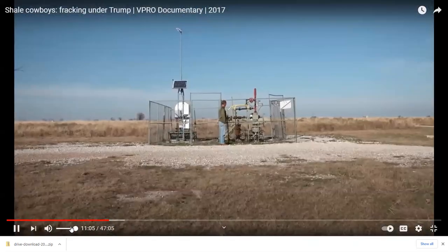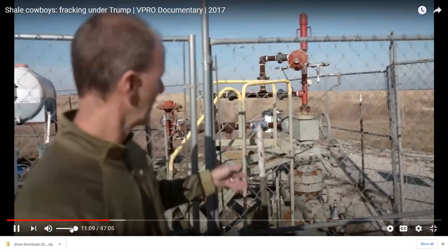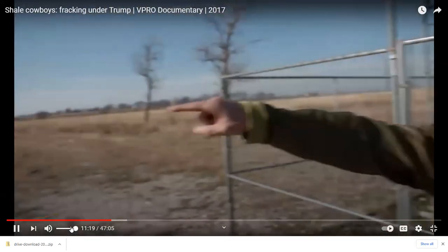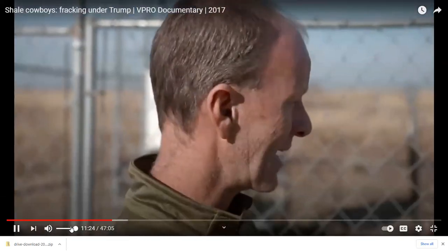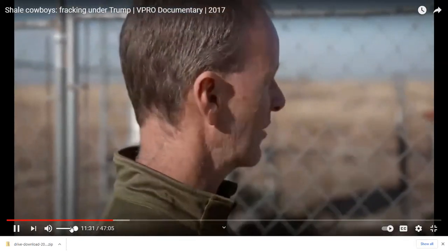This is the CW Slay #1, and this was the first well that was fracture stimulated in the Barnett Shale. And this is a wellhead so that the gas comes up and it goes underneath the ground to back by my car over here, which is the separator and the production tanks. So 16 years ago, I fracked this well with a slick water frac. And then after that, this well has been sitting like this basically for the last many, many years, without any noise, without any interference, and it's just been sitting here producing for a very long time.